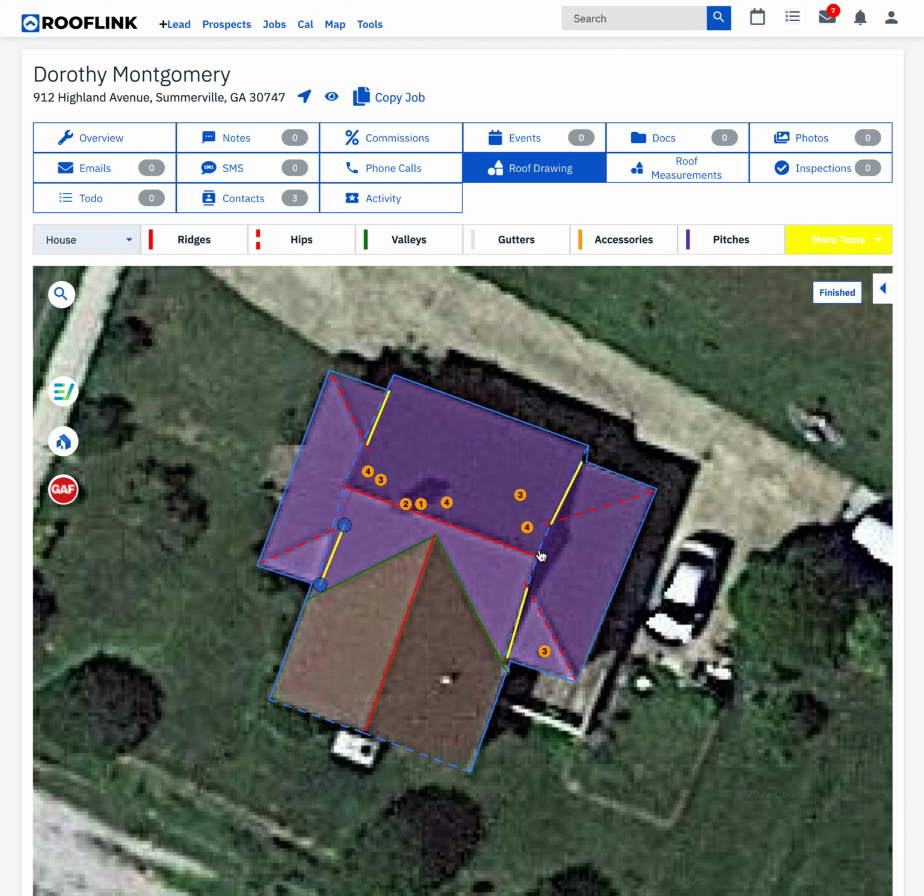Okay, so the only other flashing that we're missing here is an apron flashing that's going to go in this area that's flat. So it's a flat line, it doesn't step down, so you don't need step flashing because this is running flat against the siding. So we're just going to go in and change this to just a simple flashing line item. We're going to drop it in right there. We're just kind of connecting the dots because at all points it would be flashed to some degree all the way across. So that completes the roof diagram.